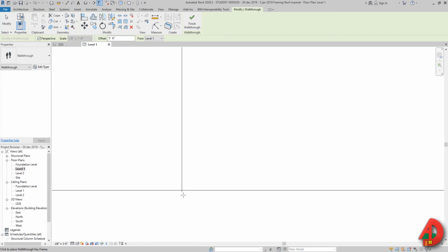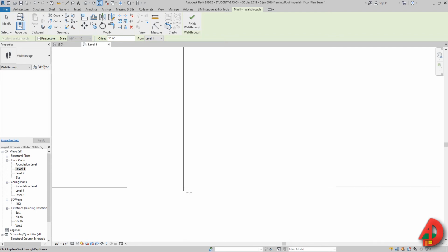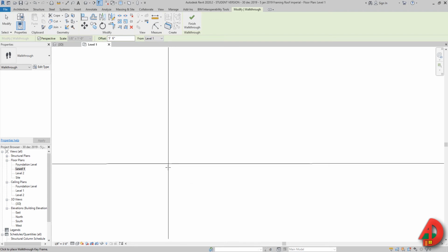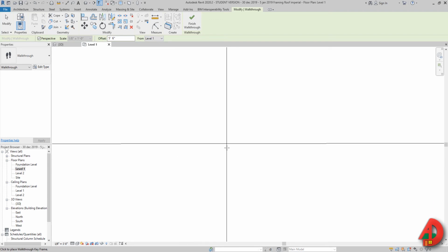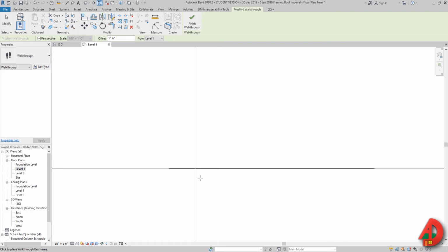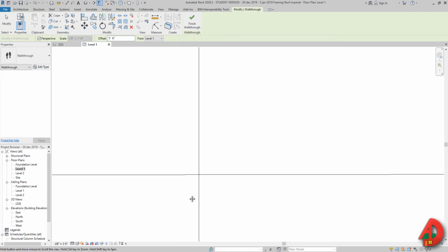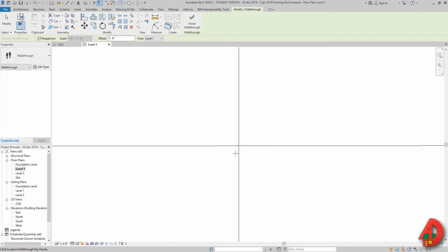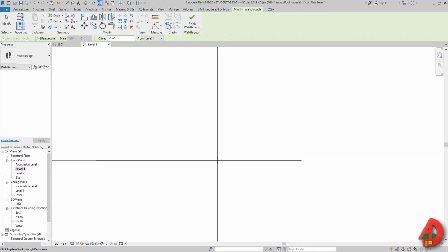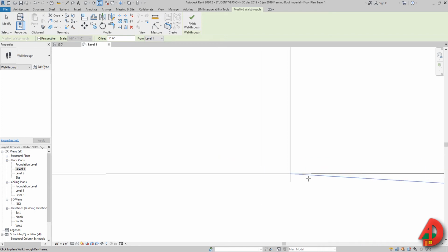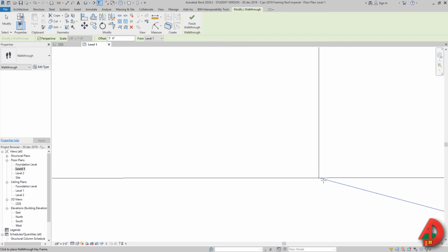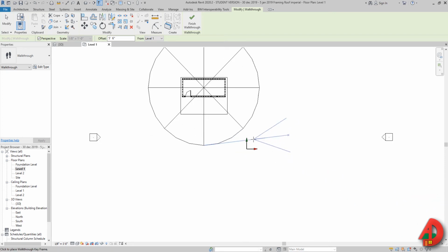And the key, if you wanna loop this video, is to try and zoom in as much as you can for the first and the last frame. The other ones are not that important, but if you don't wanna have glitches in the video, you need to try to be as precise as you can with the first frame and the last frame. So I'm gonna zoom in as much as I can, and then I'm gonna click here at the intersection of these two lines. So right about here. Then I'm gonna zoom out. It's gonna take a while, or I can double click on the middle scroll mouse.